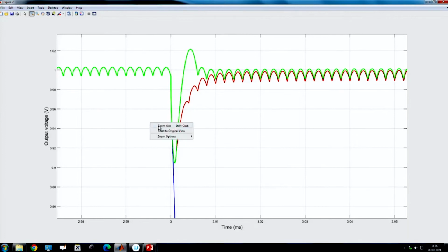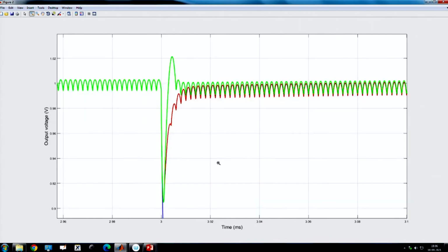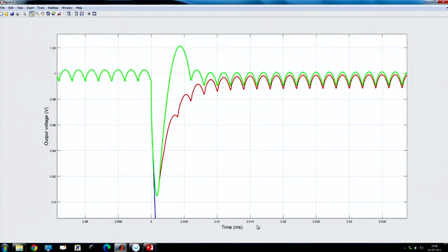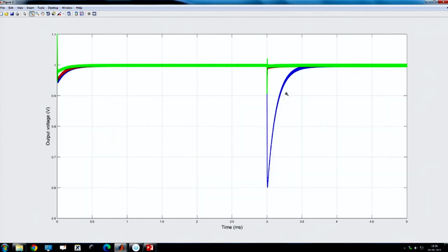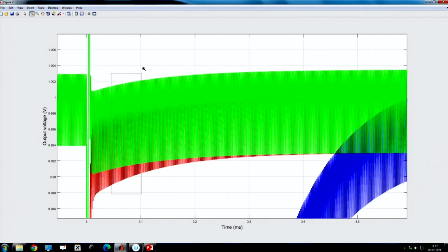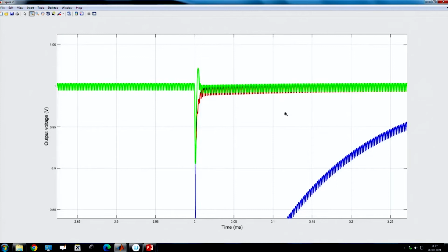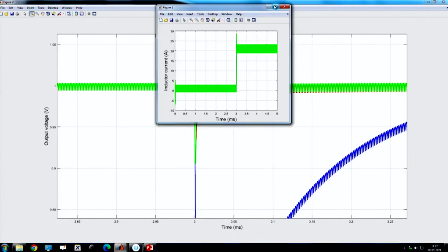Yes. So, you see, when we consider our large signal tuning, it is recovering in almost 3 cycles, whereas the regular current mode control with load feed forward is taking some more time, and it is somewhat sluggish. So, it takes a few more cycles to reach steady state, okay. But it is good that both are giving fine results with load feed forward, but optimal gain makes it even faster, right. So, you can just check it here.